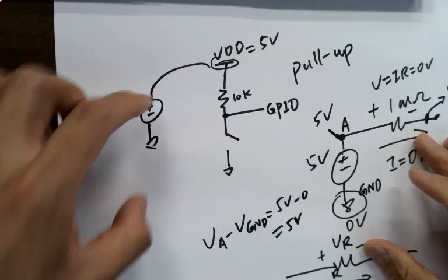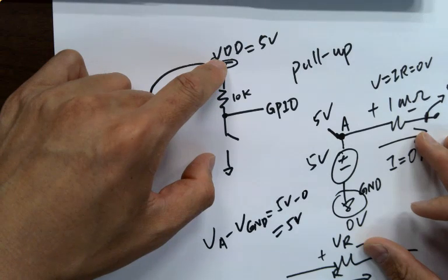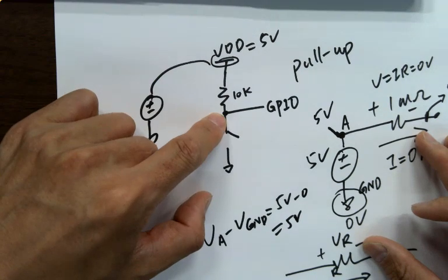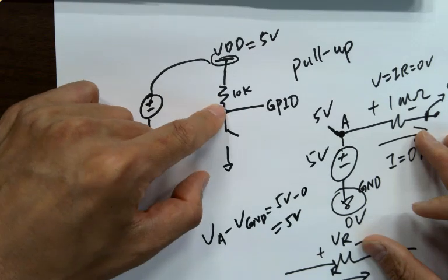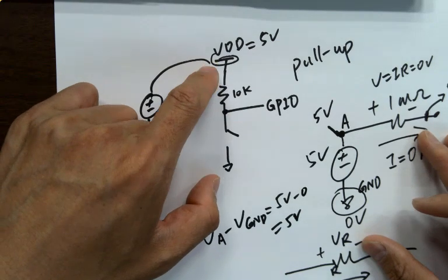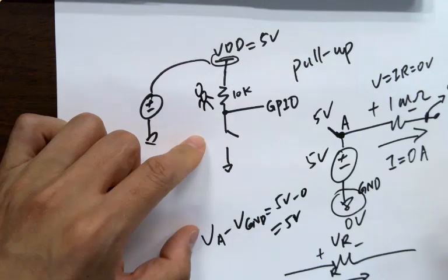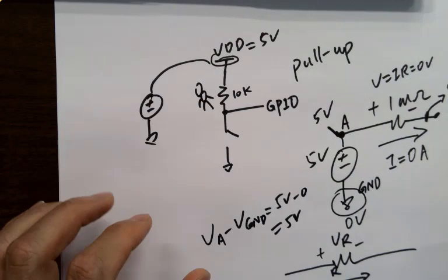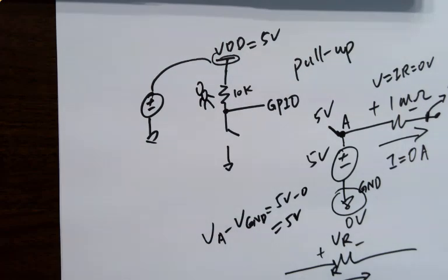It's going to be the same thing as this. Supplying 5 volts to it. What's the voltage here? 5, because there's no current, no voltage drop, right? So that's why it's pulling this up to 5 volts, even though there's no little person in the circuit pulling it up. No, it's just pulled up by the voltage.